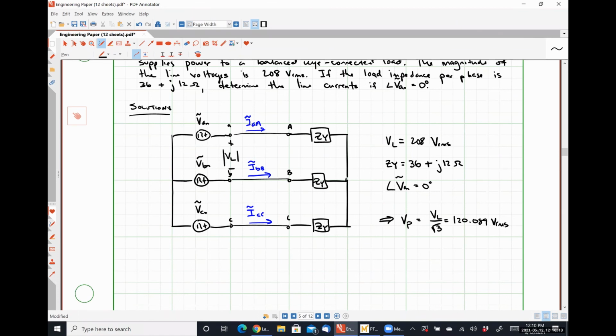And so you split that single phase into 2 different 120 volt systems by putting a tap at the center and setting that as your ground. So that technically you have access to, from that ground point, positive 120 and negative 120 volts RMS.